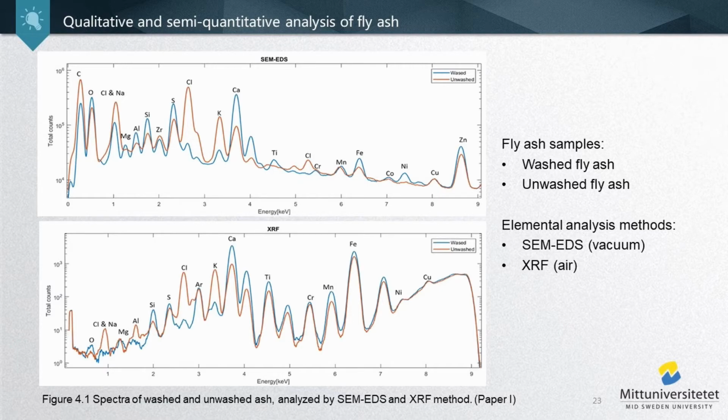But the SEM EDS measurement is performed in a vacuum chamber, while the XRF measurement is performed in air. So the SEM EDS gives a much better resolution for the light elements.